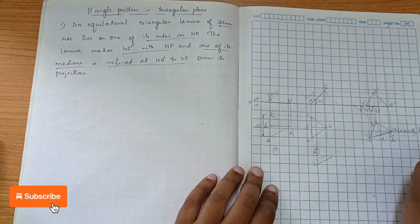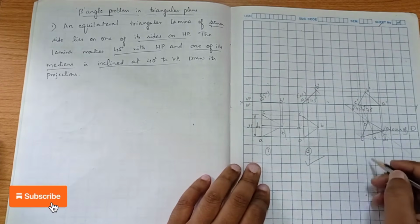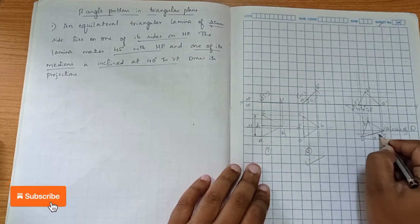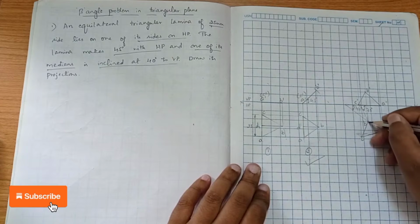Then we will be drawing a locus. We mention it is the locus of D. After that, we measure again from B to D, and we cut the arc on this locus line. So there is a locus line here, right? On this locus line we cut the arc. After cutting the arc, we join BD.